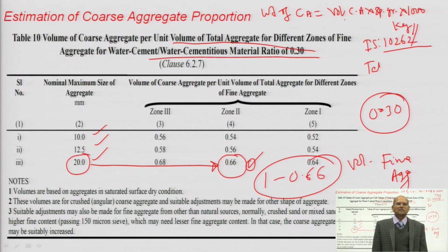So, now we have got the weight of all the materials like cement, coarse aggregate, fine aggregate, admixtures, and all these ingredients. But that aggregate is for surface dry condition; in actual condition there will be some water absorption in coarse aggregate and fine aggregate, and similarly you may have some moisture already present in the aggregate.